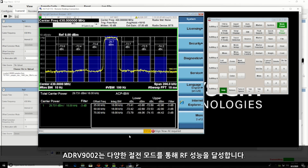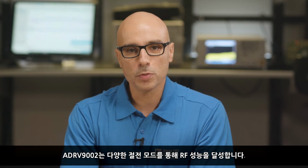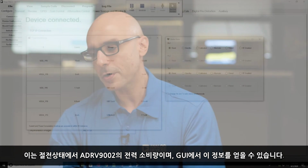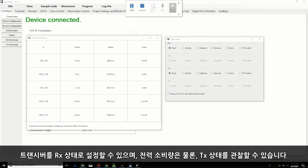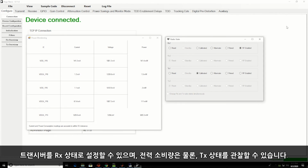The ADRV9002 achieves its RF performance with an array of power-saving modes. This is the power consumption of the ADRV9002 in sleep state. You can get this information from the GUI. You can put the transceiver in RX state and you can also observe its power consumption, as well as TX state.